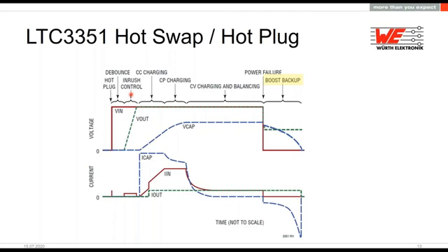So first in constant current mode. So here's the constant current charging. You see here the voltage at the capacitor rising. Here's the input current, so it's quite high as defined. Then you do it in constant current mode, then in a constant power mode. So it's here when there's some bump, it's constant power. And then at the end in a constant voltage mode. And the IC is doing some balancing.